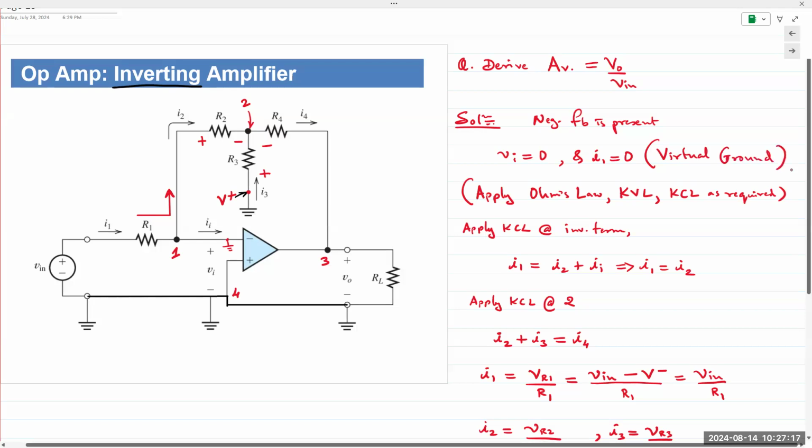It is because the op-amp has infinite input impedance. So an ideal op-amp does not allow any current to actually enter the op-amp. If it's not entering the op-amp, then basically the input current is 0. Also, if you ground one terminal, either the inverting or the non-inverting terminal, connected directly to ground, that terminal has a potential of 0.